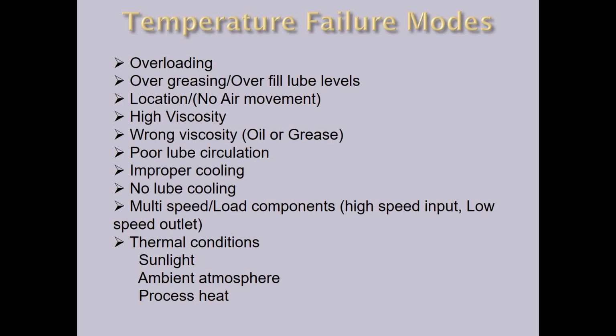And then you have thermal conditions, sunlight. I was at a plant in Texas showing this one on their pumps in their tank farm in the mornings before the sun came up. The pumps were about 118 degrees Fahrenheit, and the motors are around the same thing. But when the Texas sun was shining on those pieces of equipment in the afternoon, they were 160 degrees, which that extra temperature on the pump housing was causing the lubricant to fail like 3 times earlier.